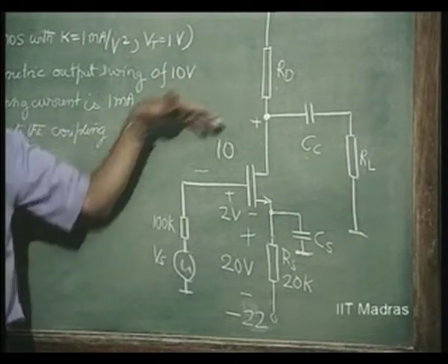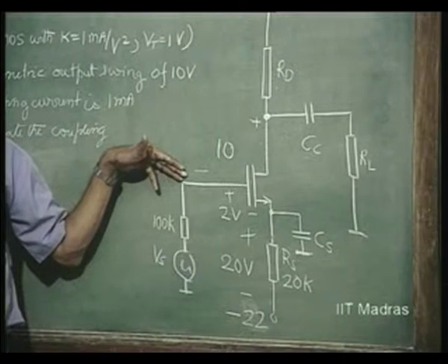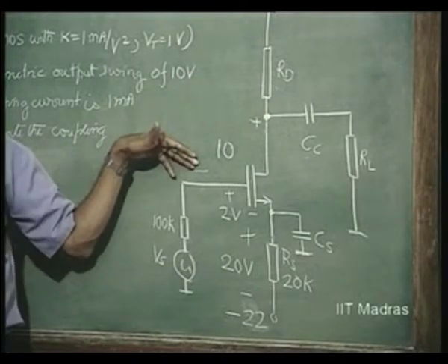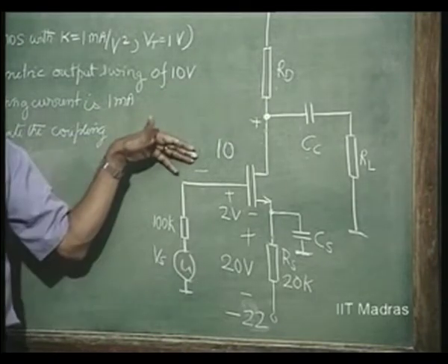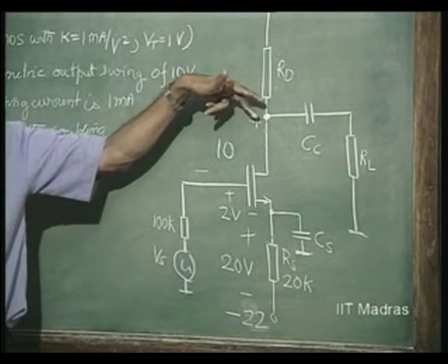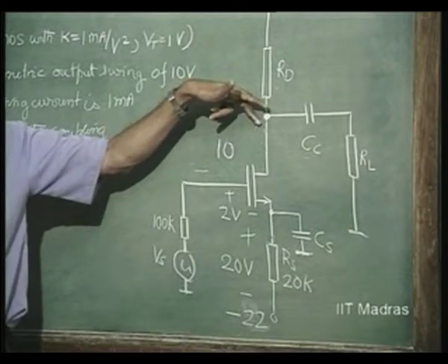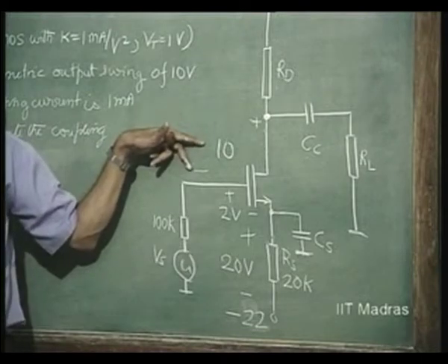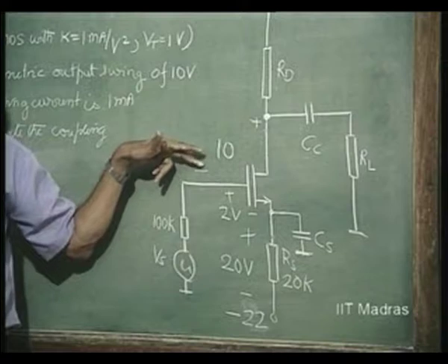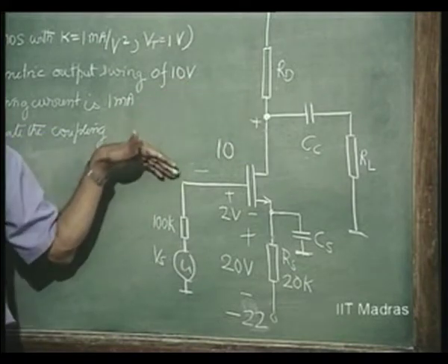So, if this is 10 volts, is this clear? On one side before it goes to triode region, right. So, this is very nearly equal to 10 volts. Actually, we know that this can now go to minus plus 1 volt. So, there is a swing possibility of 11 volts on this side. So, anyway, I am fixing this as 10 volts.